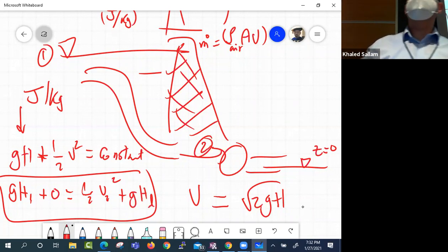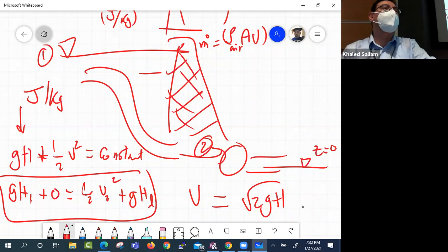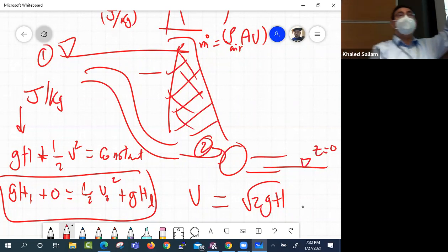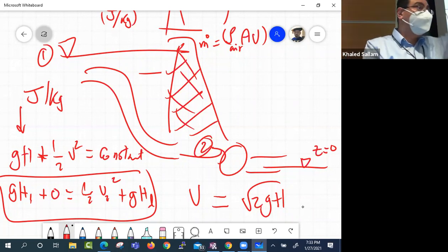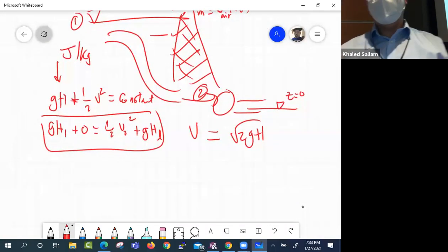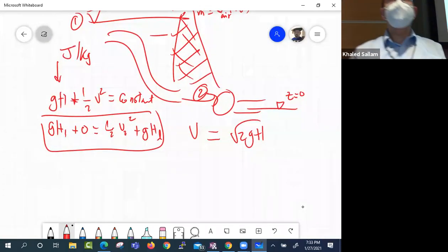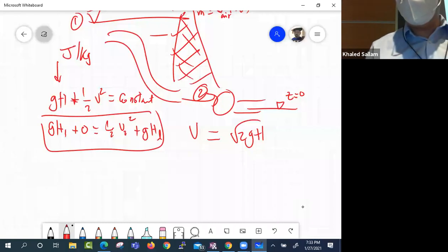And they will tell you the losses in this pipe is like 4 meters of water. So you have a dam that has, say, 50 meters behind, and the piping and all the kinks and the elbows and stuff is like 4 or 5 meters. It takes from the actual head available to you, right? And if you remember from your Fluid 1 course, how did we calculate this H loss in pipes and elbows and valves and stuff?